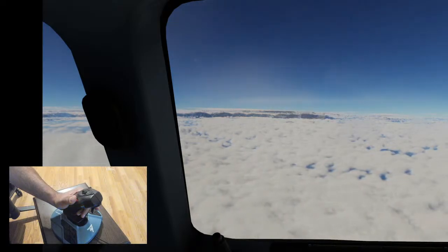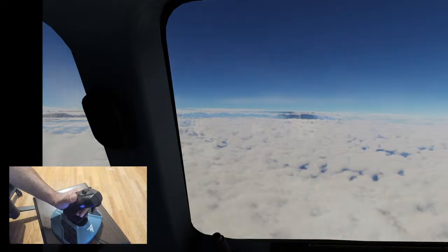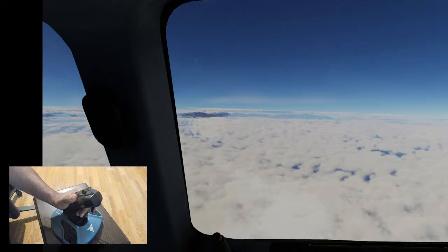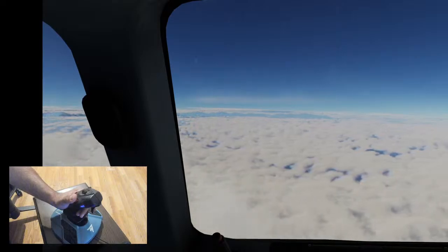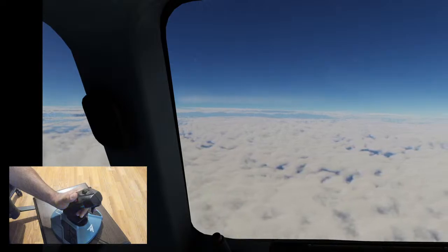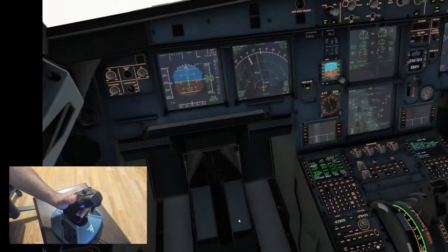If I have some suspicions about an unstable approach or unstable landing, I will go around. I will just punch the throttle with TOGA mode. After TOGA, I will climb as per the missed approach procedure, and then I will do the go around. And then I will try again one more time, and from the cockpit I need to give some brief information.